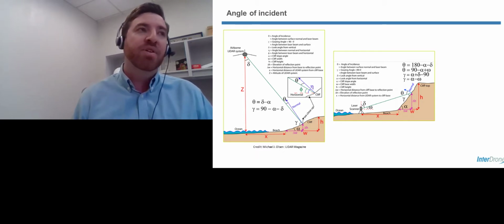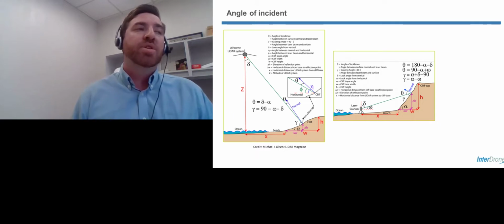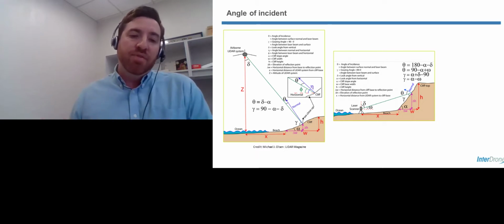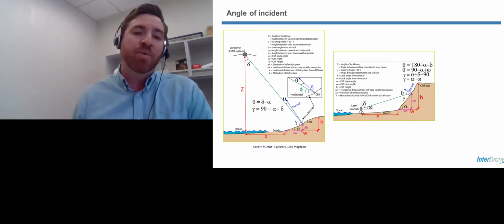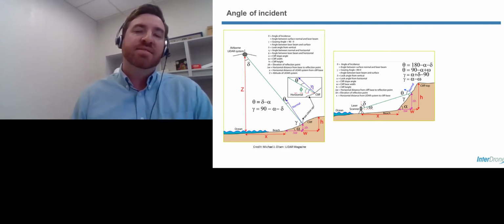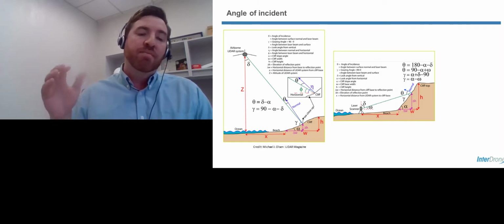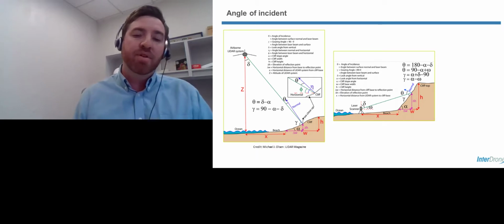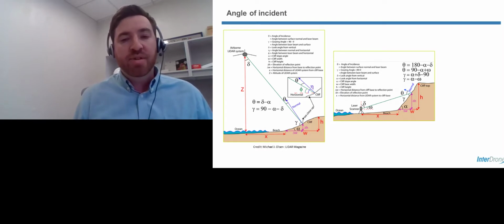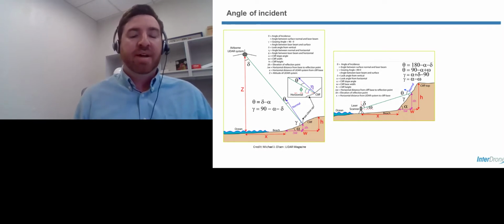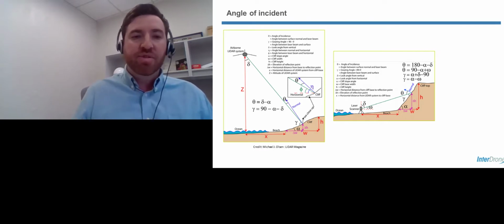Typically, those plug in really well when you have vegetation involved. So we're talking LiDAR right now, where we can penetrate down into the vegetation. And when it's offset from the road significantly, mobile LiDAR, based on its setup, which I'll show you in a little bit, may not get as good an angle to penetrate down to the bare earth. Because remember, at the end of the day with point clouds, which we'll talk about, we want to filter out the vegetation and we want to be left with the best representation of bare earth as we can. So angle of incidence is really important to us.